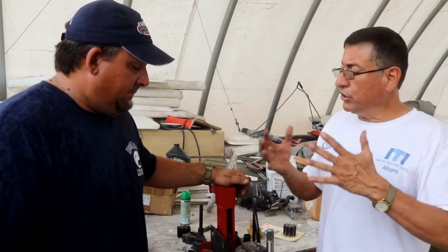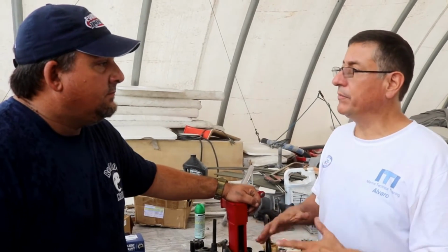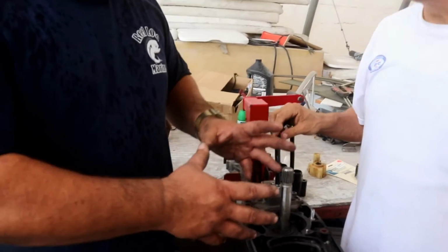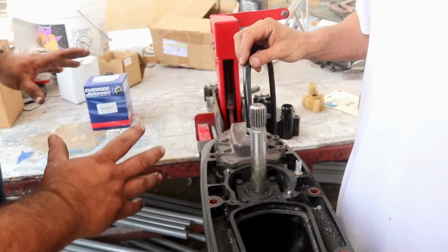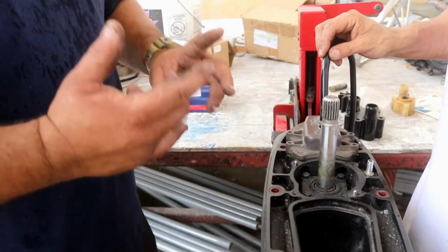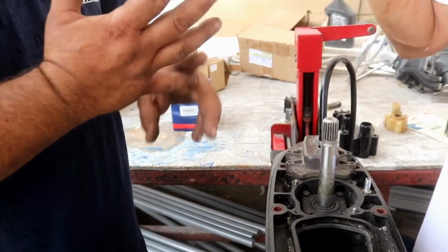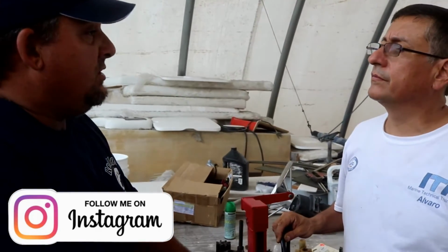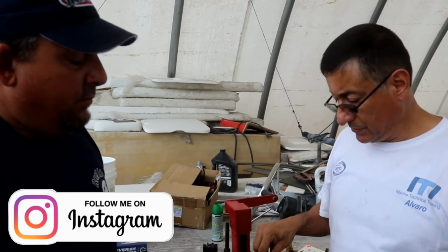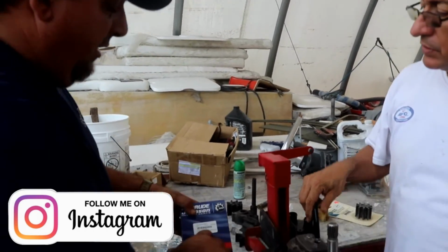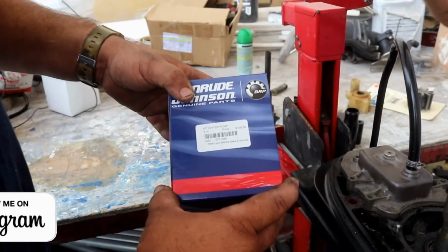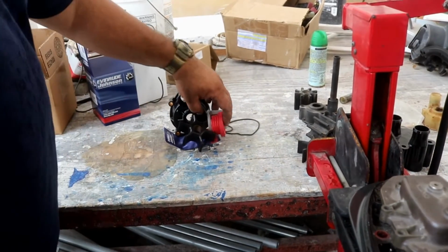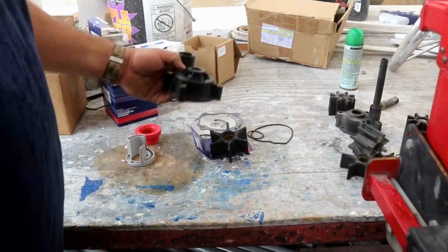Danny, we are going to do the full service on the raw water pump in this unit. First step: you take everything apart, which we've already done. To know exactly what water pump you need, look at the manufacturer specs and the service manual. You need the model and serial number for reference, because there are different applications for different pumps. Once you do that, you know the part number and you buy the unit. Then you open it up, and those are the parts that you receive when you order the kit.